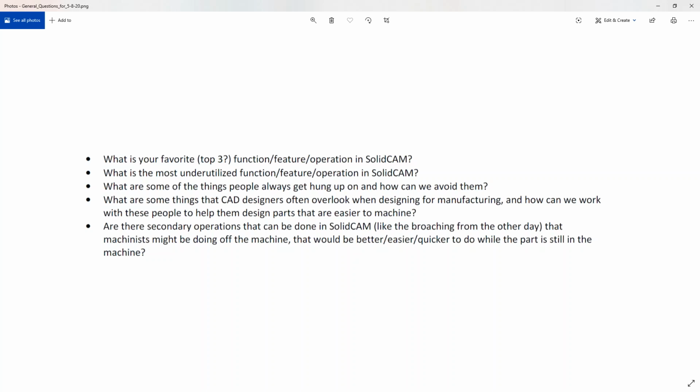Now, the funny thing is, with those secondary engraving machines, to do a part number, we did a time analysis on it, and it is quicker to do it inside of the machine than it is for that secondary engraving machine to do it. Plus, you have to have a second person to run that machine, where when you do the engraving inside, it's already done there for you.